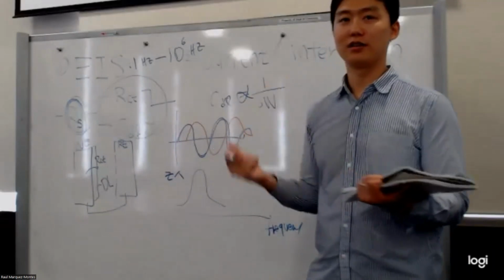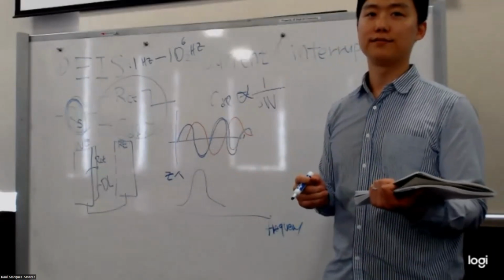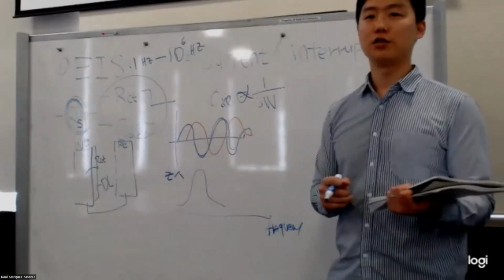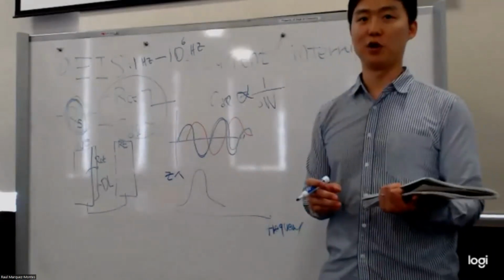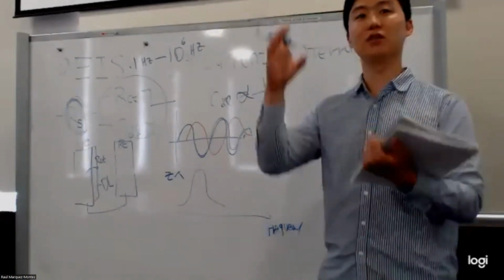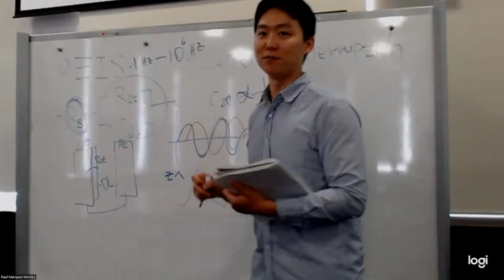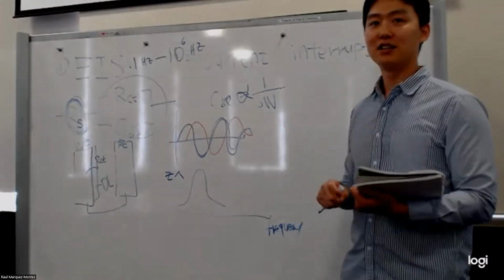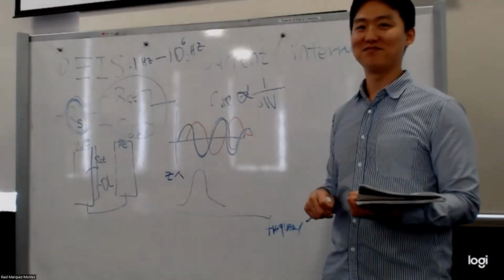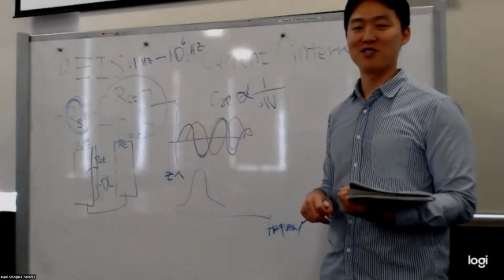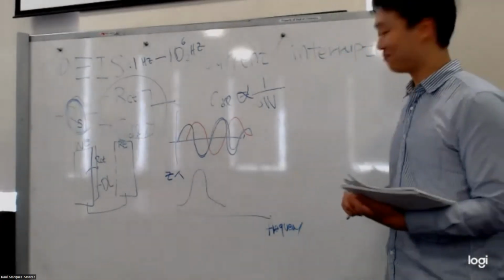Could you also have multiple RC elements to fit the curve? Multiple RC circuits, yeah, it's possible depending on the electrochemical system. If we have multiple interfaces or multiple electrochemical processes in series, we can add more RC circuits additionally. Okay, I'm just asking because I work in batteries, so we typically have to use multiple. Yeah, two or three more RC circuits, it could go up to like...